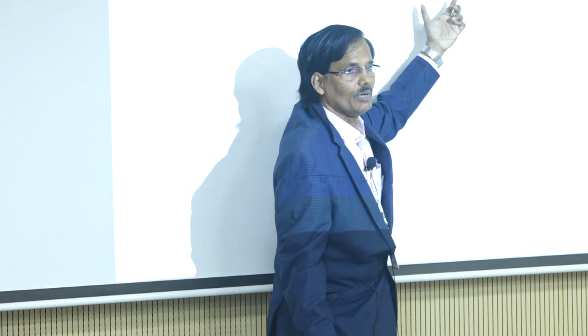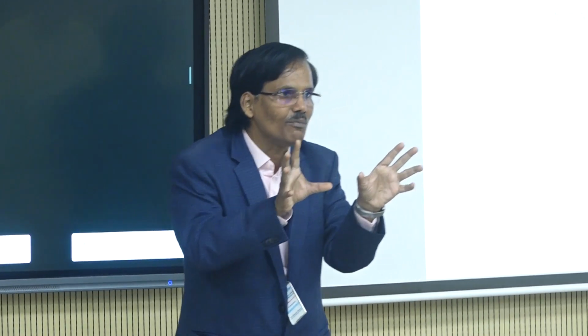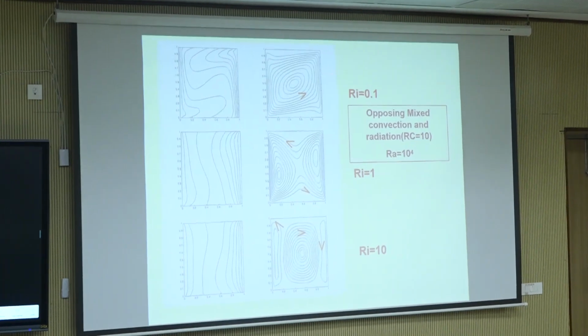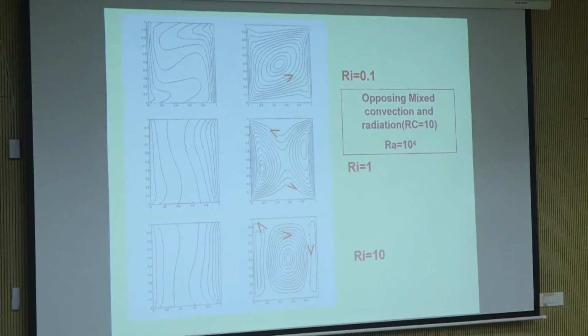So the adjacent fluid will be coming to that. When a temperature gradient is there, naturally flow will occur. Now the question is, when the middle phenomenon was there, some local gradient was there. Now in the presence of radiation, this gets homogenized. Radiation tries to make the temperature homogenized. As temperature is getting homogenized, the gradient which was existing is completely lost. So this middle cell is going out. This is the finding, and this is the effect of radiation.